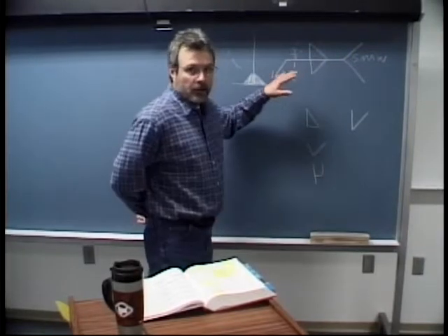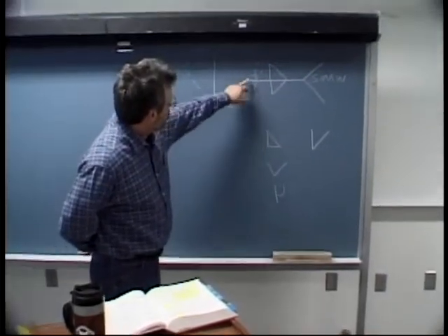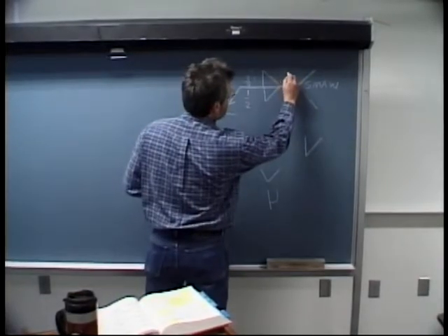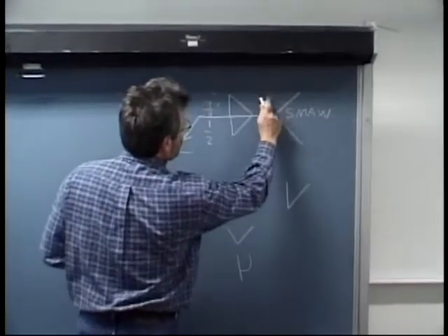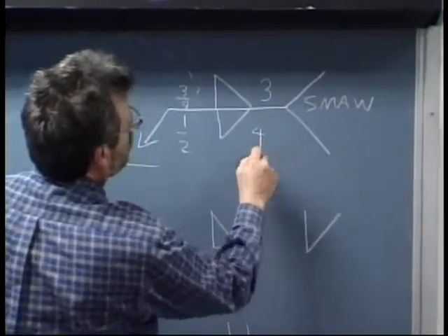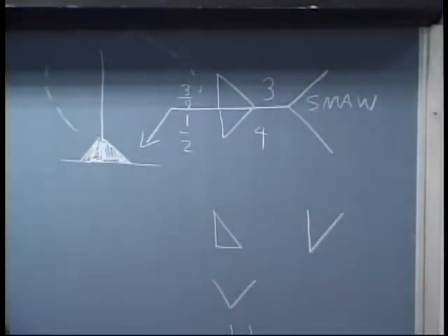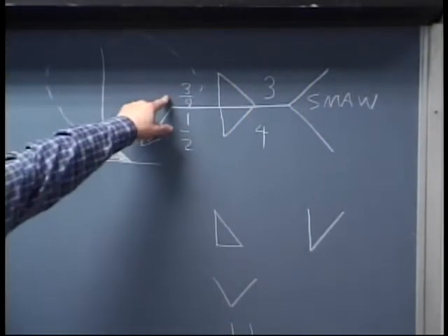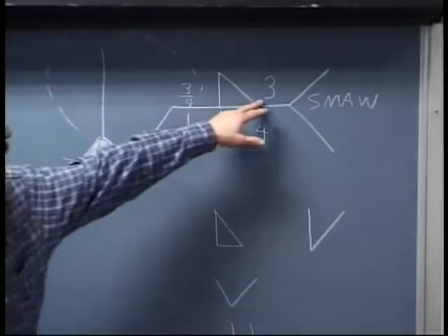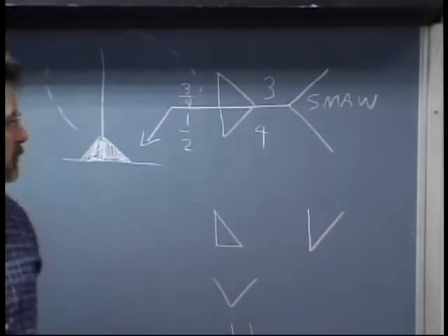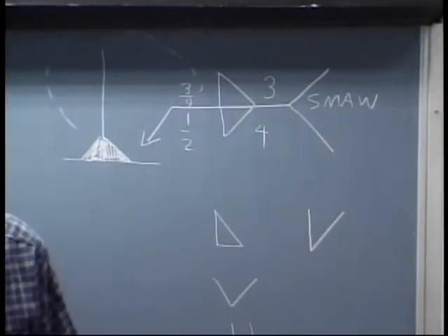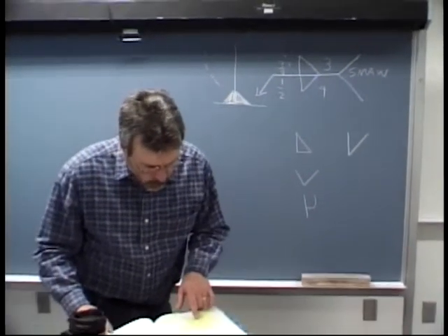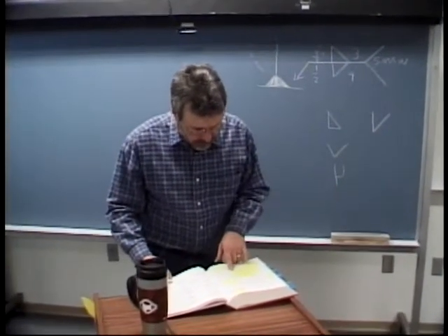So here on our sample, we have a 3/8 and a 1/2, and then we're going to put the length, say 3 inches, well, because we don't have to put the inch marks, and 4 inches. So that's how it would appear on a symbol. 1/2 inch fillet weld, arrow side, 4 inches long, 3/8 inch fillet weld, other side, 3 inches long, and we're going to weld it with shielded metal arc welding. Okay. If no length is indicated, the weld should run the full length of the joint.